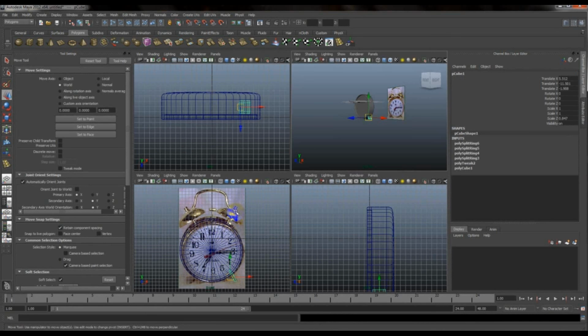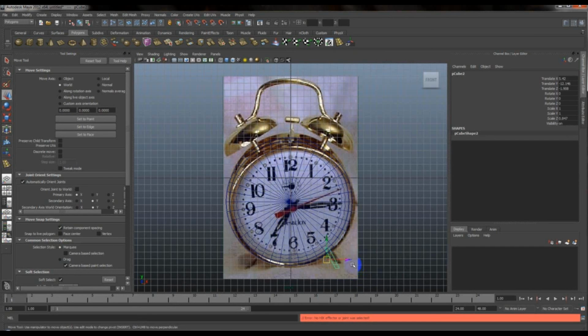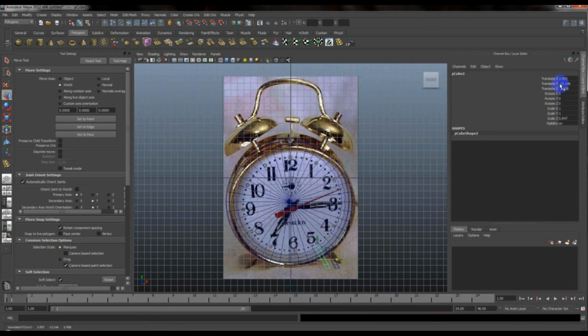object, and I'll try to duplicate it and make a reflected duplication of this object on the other side. So I will click Control D. After that I'll go to scale, maybe Z, and make it negative. Sorry, not Z, it's scale X. Yes, X. And instead of 1 I'll choose -1 so that it will be on the other side.